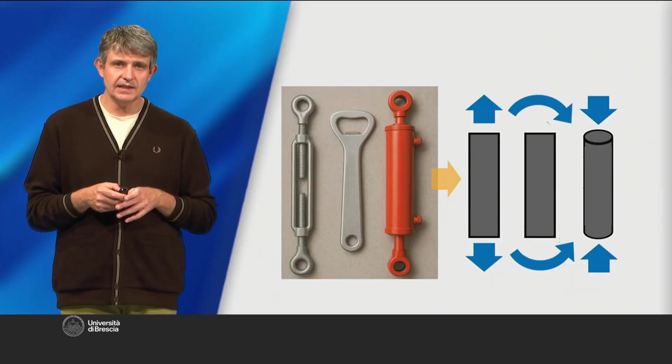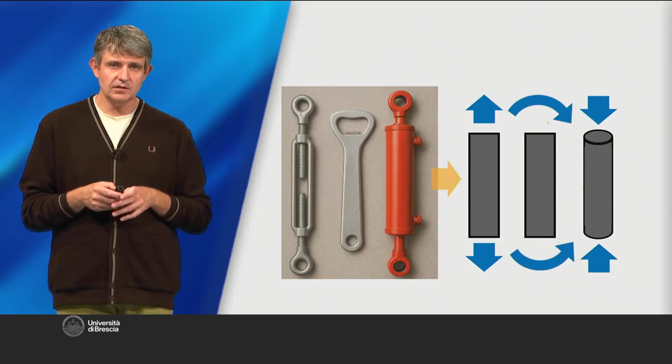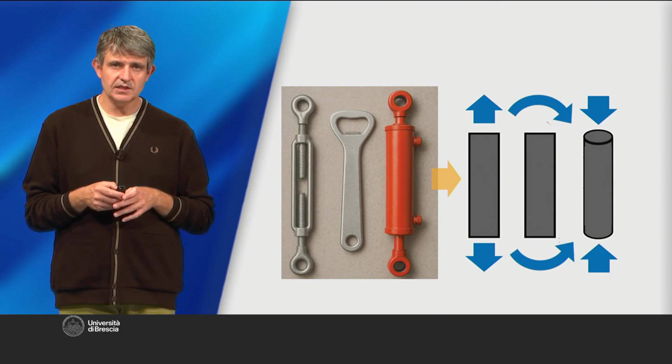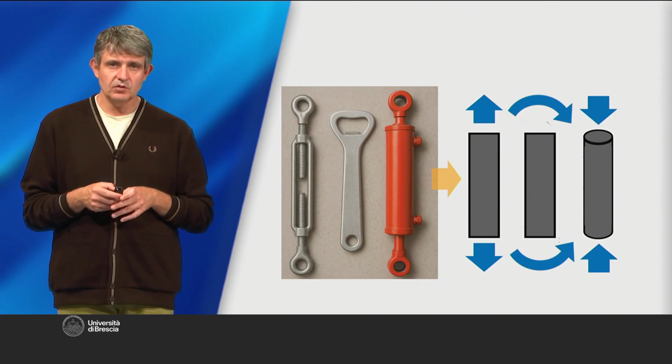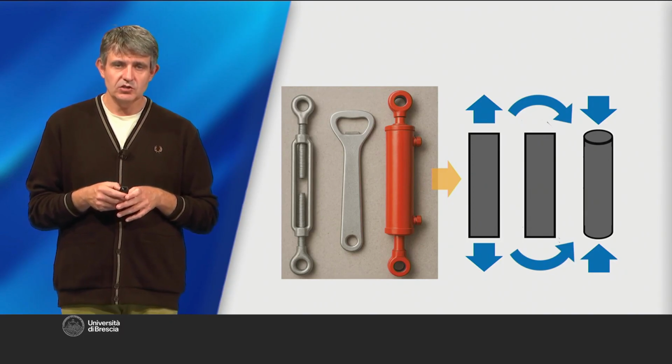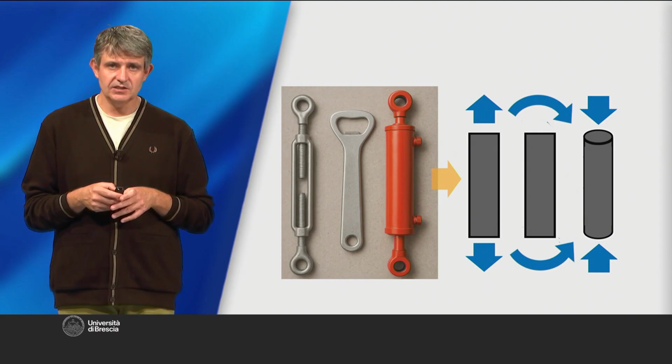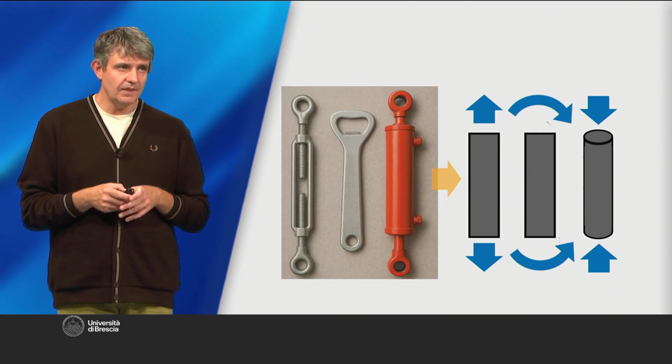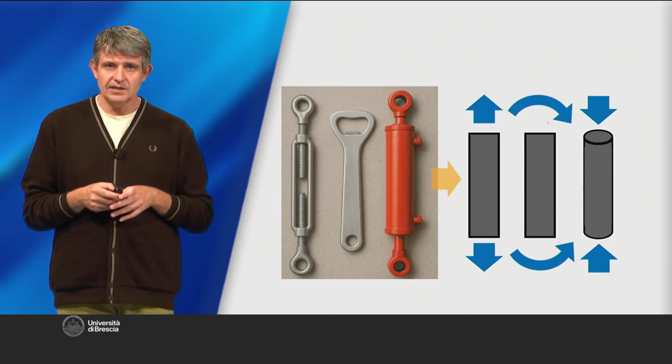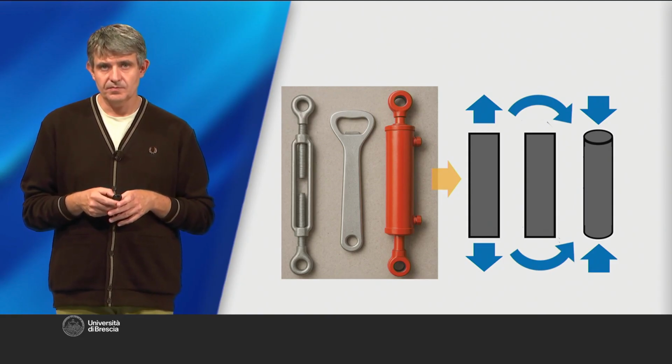It is important to clarify one point. In these initial phases of material selection, we are not interested in a precise, detailed description of the product, but rather in a simplified model of it. For this reason, even for complex structures, we will refer to classic engineering cases, and so a tie rod will be associated with a tension bar. The handle of a bottle opener will be treated as a bending lever, and the body of a hydraulic piston as a compression column. The first case concerns the choice of materials for the shaft of a golf club.